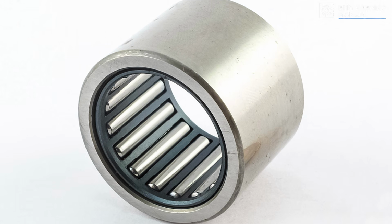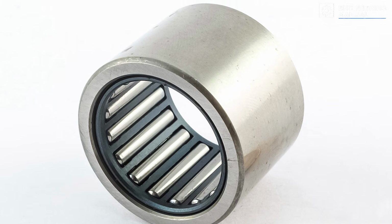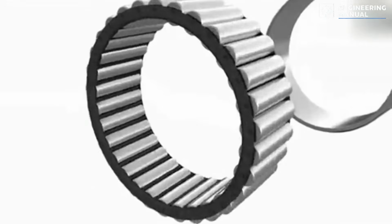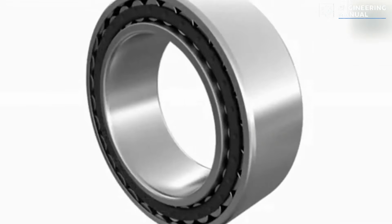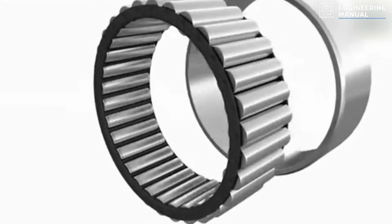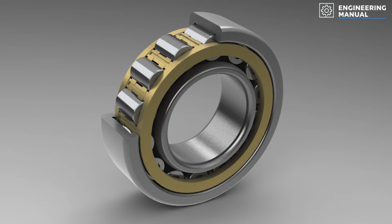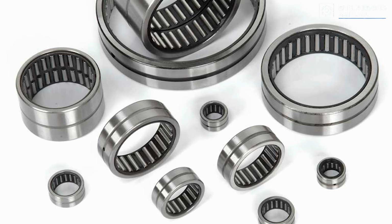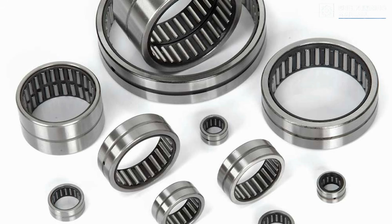Instead, they made them extremely long and extremely thin. Needle bearings use slender cylindrical rollers whose diameter is only a fraction of their length. The result is remarkable. They provide line contact, similar to conventional roller bearings, while occupying only a tiny radial cross-section. Few bearing designs achieve more load capacity from less space.